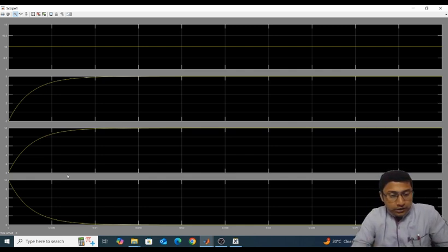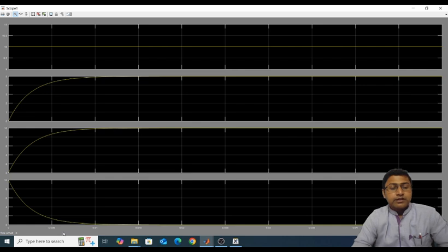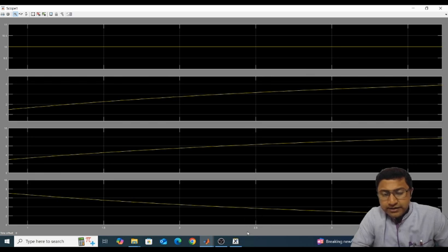Look, this timing, 0.005, is actually 5 millisecond. We will consider the timing of 2.5 millisecond because it is the time constant. More or less the half of this portion is 2.5 millisecond. If I zoom this portion of the second parameter, the inductor current, we will see that this point, after zooming, is 2.5 millisecond.